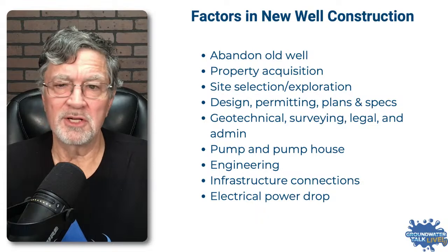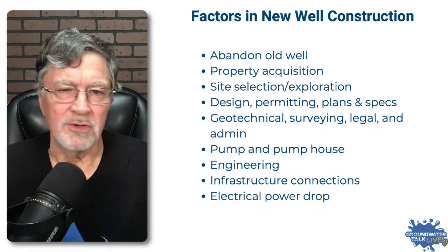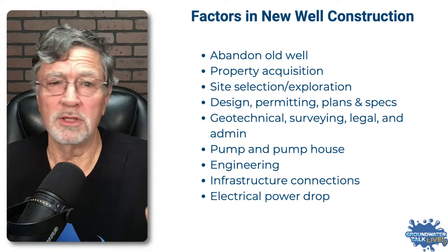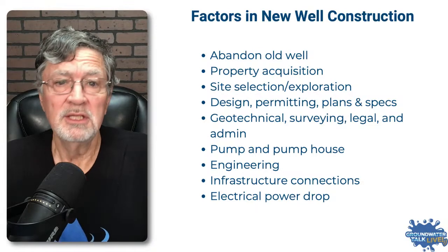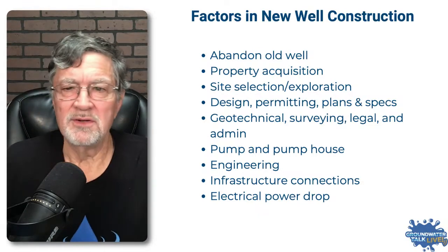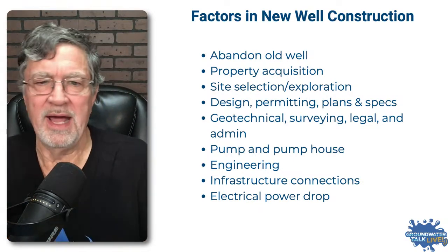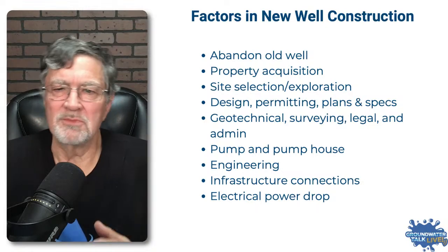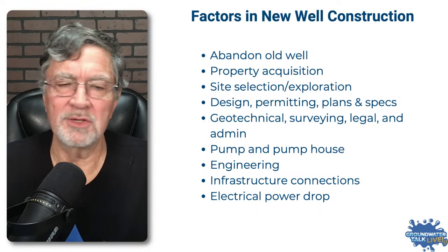So you do your site selection, your exploration, so your test borings, and you do your well location study. So we're really looking at the potential for contaminants, other wells in the area to determine what kind of production we can expect from that well, and then design, permitting, plans, specs. You need to bid all that out. You're going to need to do some geotechnical survey. There's going to be legal and admin costs.